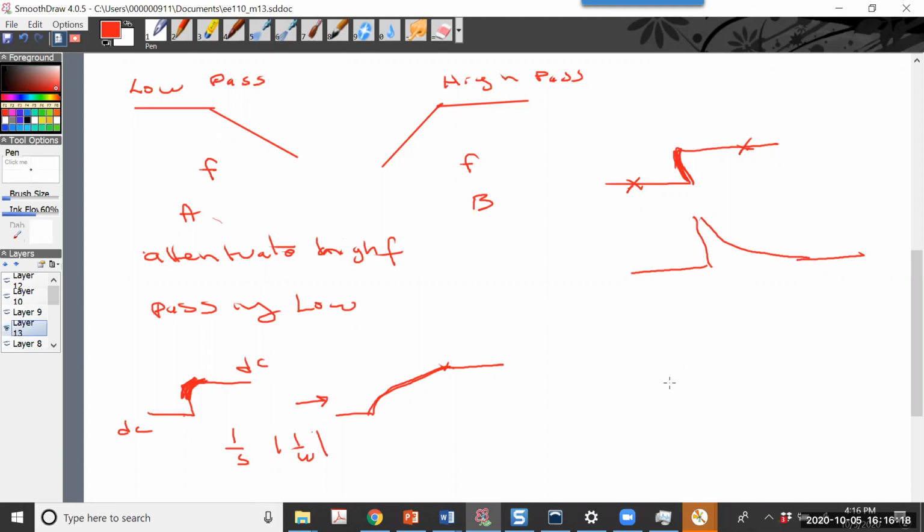Now, yeah, there's questions. High pass filters tend to have a delta function and something in the opposite direction that starts at 0, goes to something and comes back to 0. Now you could have an inverting high pass filter, and now we're talking about time. So a high pass filter has to have the original thing, and then it has kind of a low pass response built into it. But with the two of them, you get edge detection and you are blocking DC.